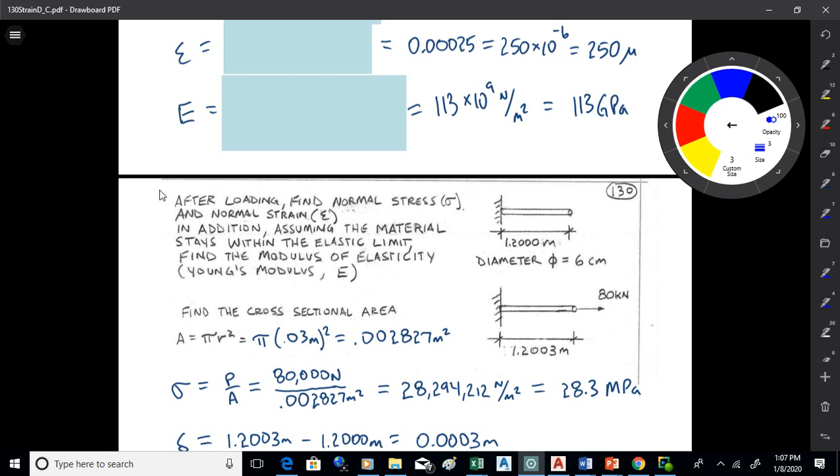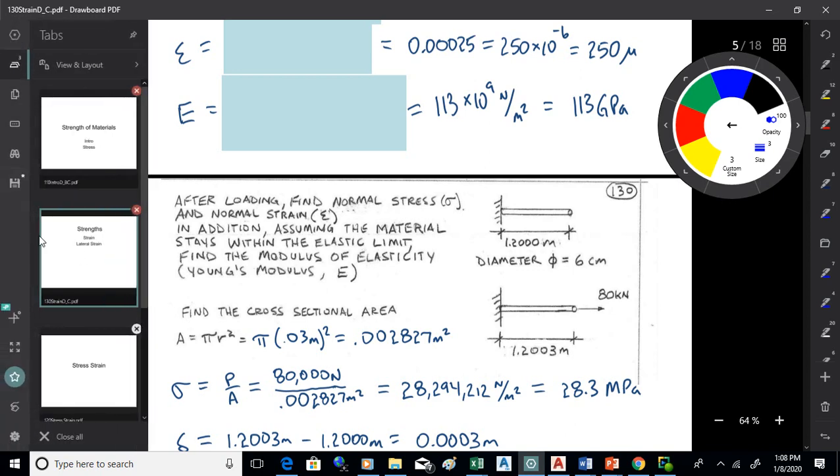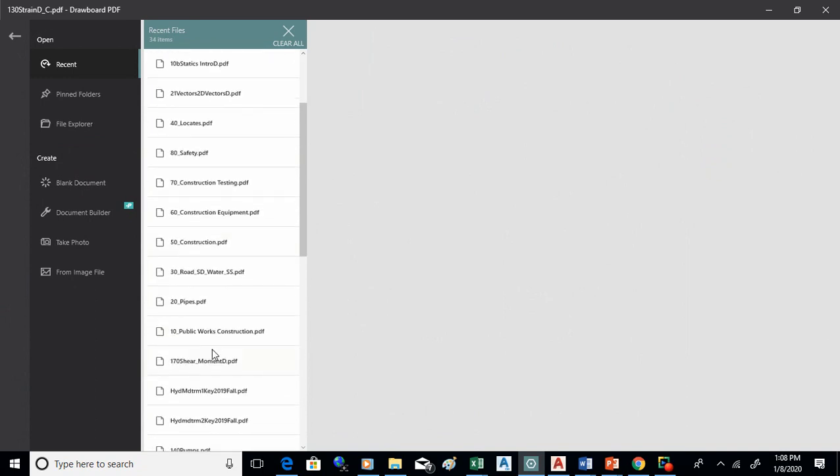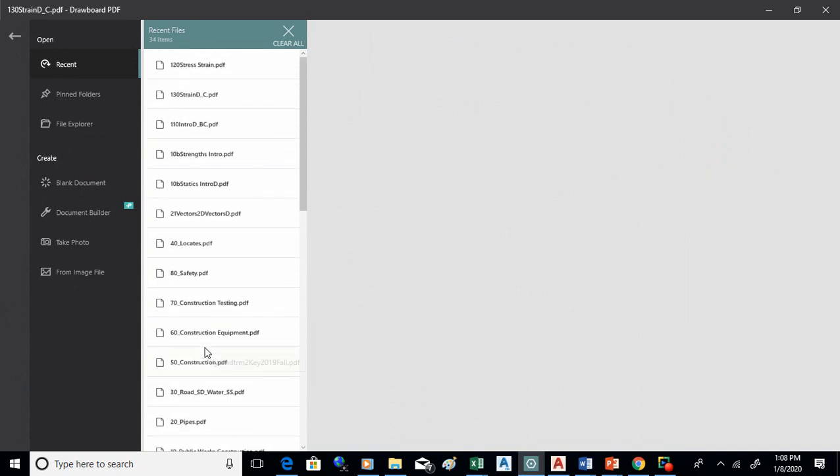Now, if you can kind of keep track of what units you're dealing with. I think if I remember right, normally when you're doing metrics, you measure the load in kilonewtons and the dimensions in millimeters. That's normally how they do it in metric. And I think a kilonewton per millimeter squared, if I remember right, is a gigapascal. I'm not 100% sure on that though. I can't ever remember this stuff. So being as I can't always remember how these units combine in metric, what I do is I just go to the fundamental units, newtons and meters, run it out, and then I look at it and go, okay, that's a meganewton or a megapascal or a gigapascal or whatever. So that's normally how I handle that.